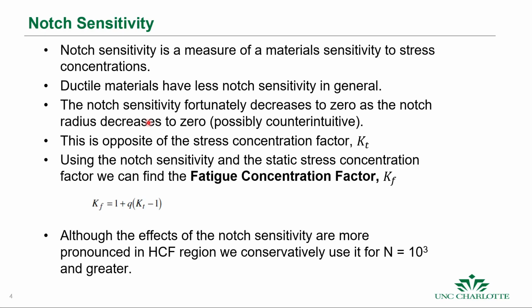And this is the equation to calculate our fatigue concentration factor. We have this equation here where we just add 1 plus this notch sensitivity parameter, which we'll show you how to use, times our stress concentration factor from our static analysis minus 1. Q is the ratio here of the fatigue concentration factor minus 1 over the stress concentration factor minus 1.